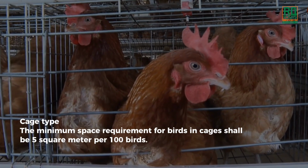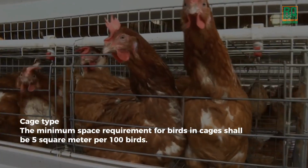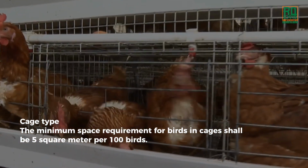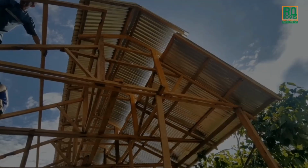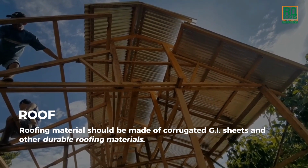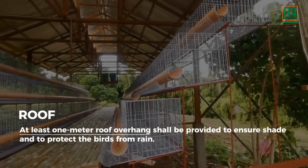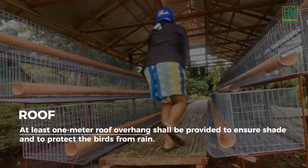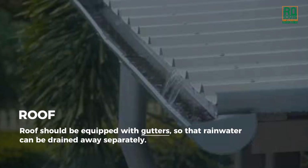Cage type. The minimum space requirement for birds in cages shall be 5 square meter per 100 birds. Structural requirement. Roof. Roofing material should be made of corrugated GI sheets and other durable roofing materials. At least 1 meter roof overhang shall be provided to ensure shade and to protect the birds from rain. Roof should be equipped with gutters so that rainwater can be drained away separately.